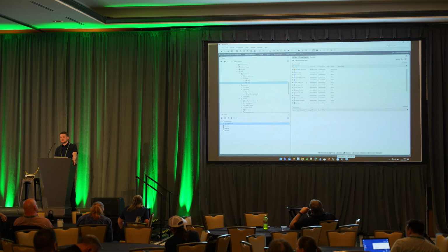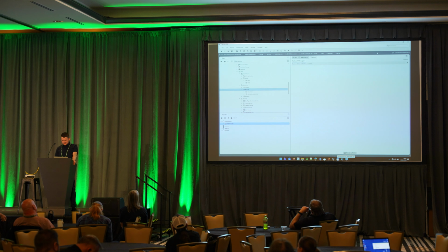The only problem is that over the web, you can see we have two room temps, right? And which one belongs to which controller? So for that reason, inside our BACnet device, we created a special configuration that we call inheritance mode. Right now we are in the standard mode.